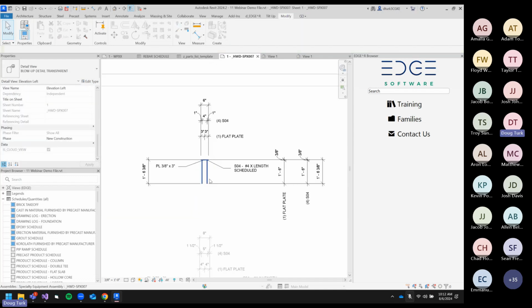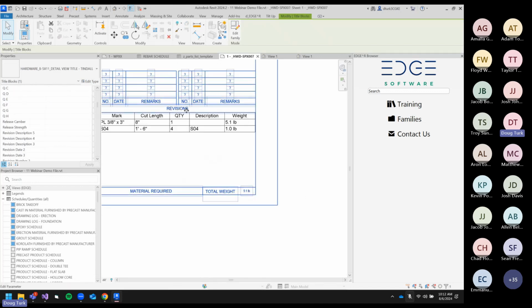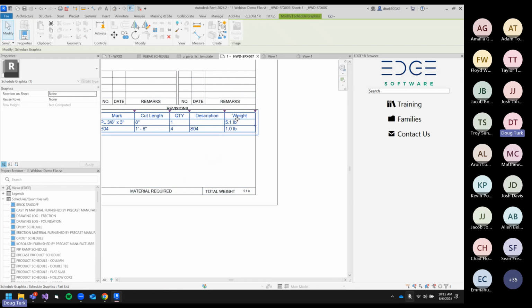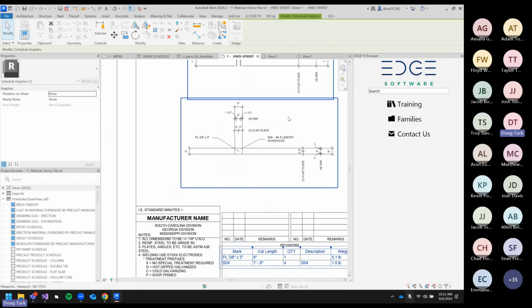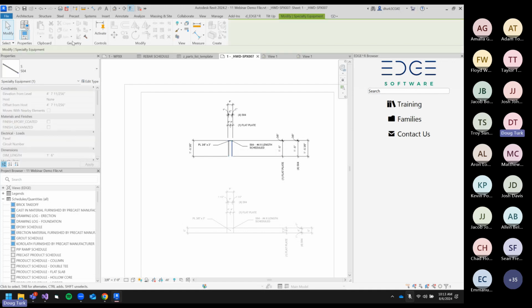So one is, of course, the TKT hardware weight, which we see down here being reported as the 9.1. But these subcomponent weights are actually being written per subcomponent in the piece of hardware. And importantly, it's only written to those subcomponents, to those raw materials going into that piece. The top level will not receive a value for this parameter for an important reason that I'll get to in a moment. And that parameter is, find it in here, HW component weight.